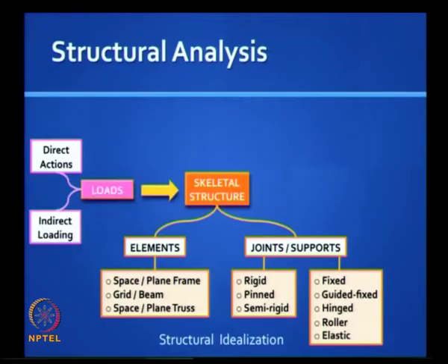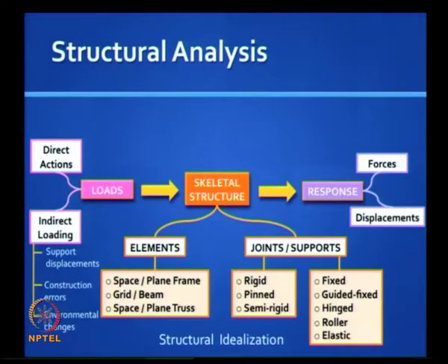On this structure we apply loads, and the loads are of 2 types: direct actions, which you indicate with those arrow marks, or you can have indirect loads, and there are 3 types as we discussed. You have support settlements, you could have construction errors, you could have environmental changes, and we are interested in finding the response of the structure, both the force response and to some extent the displacement response.